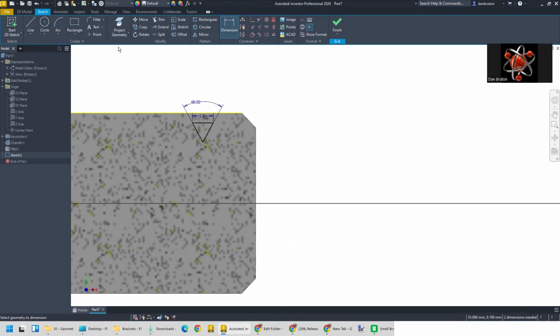Okay, the next thing I want to do is maybe move this out so we can get a good look at it. So escape, get it back over here to the cutting area. And we do want it in line with that. So we will put a line here over to there and make that a construction line and give it an arbitrary distance of like 2 millimeters. Now, let's see if we can go ahead and cut those threads.